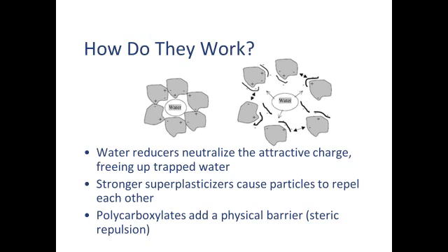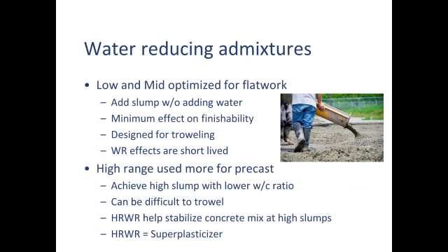And the chemistry behind them is even more complex and more sophisticated, because instead of just acting like a dryer sheet that you throw in your dryer so your socks don't stick together, these actually have polymers that coat the particles and act like a physical barrier that helps separate the particles. It's called steric repulsion. It's pretty cool technology, and that's why SCC, or self-consolidating concrete, uses these polycarboxylates. You can use a lot less water and still get a lot of lubrication, so your particles just slide around each other. Very, very potent, very powerful, very versatile. But not everybody needs that.